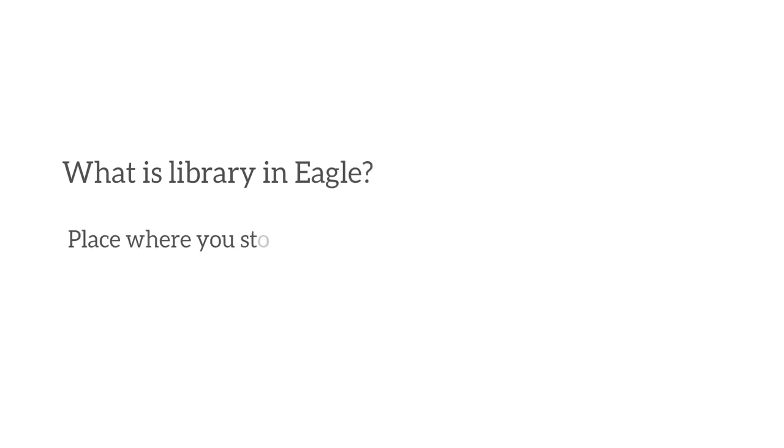If you are still wondering what is library in Eagle, I will give a brief explanation. So, basically, libraries are places where you store all of your parts in Autodesk Eagle. Each part will contain a device, symbol, and package. A library need not contain only real components. Ground or supply symbols as well as drawing frames can also be stored as device in a library.